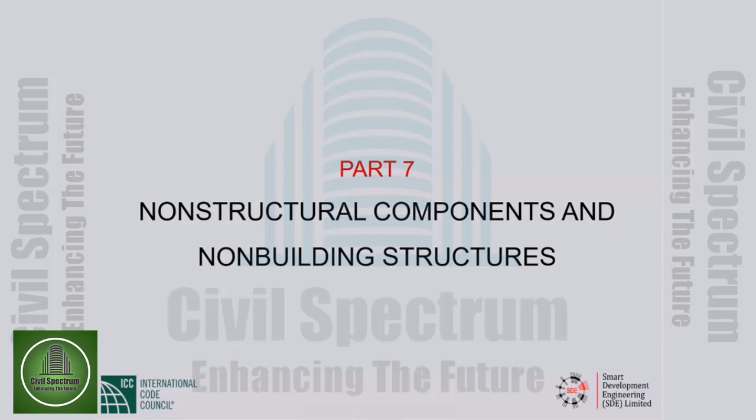And then I start with the concept of the response spectrum. From that, we go to design spectrum, and in the discussion of the response spectrum, this constant acceleration, constant velocity, and constant displacement will become very clear.